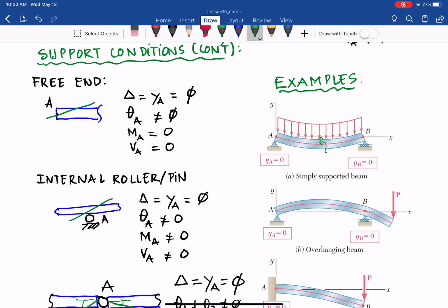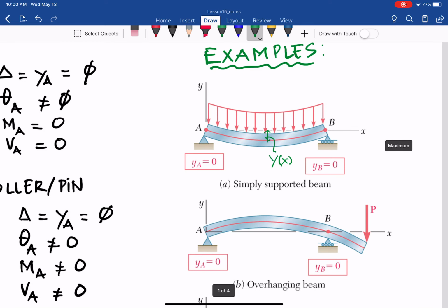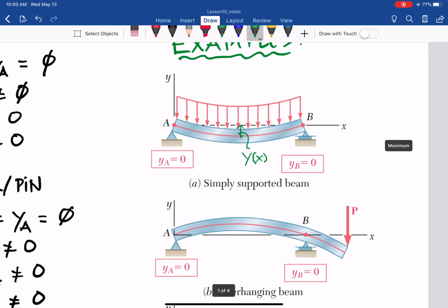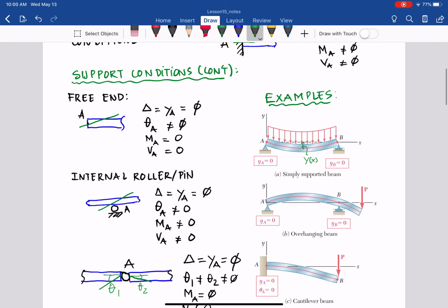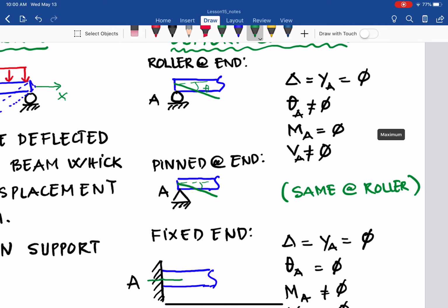here, we have a deflection at that point, and that depends on how far it is from point A. You see the origin, where that point is located, the deflection will not be the same, and it will be changing. So starting at A, it's 0, because the deflection is 0, because that is a pin support, based on the pin-and-roller support condition we are talking about here, yA equals 0.